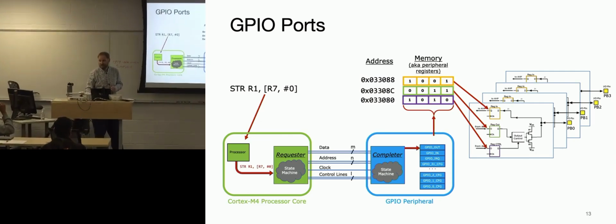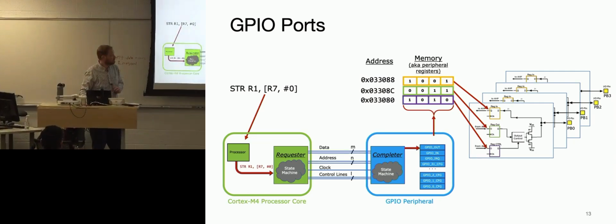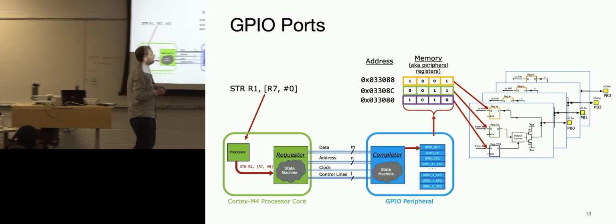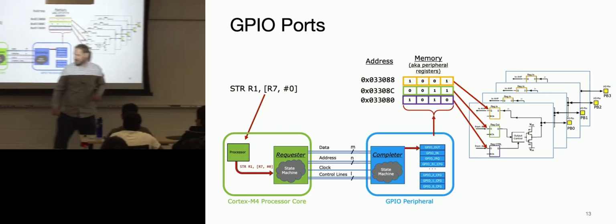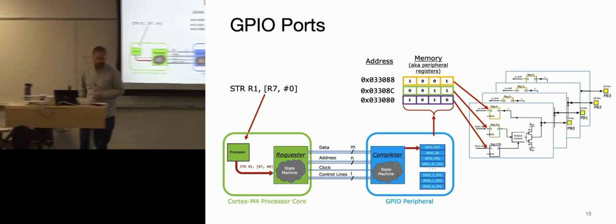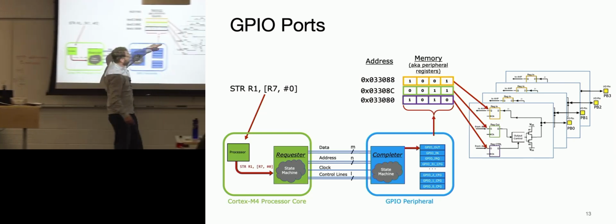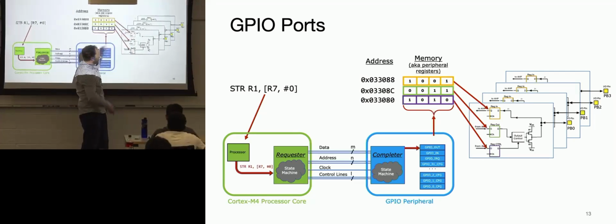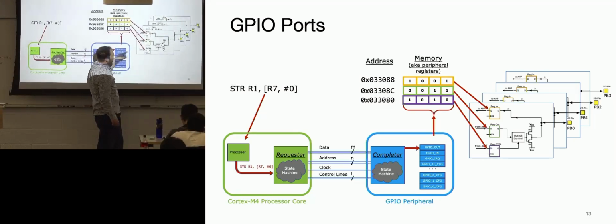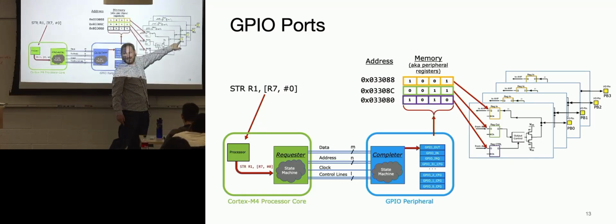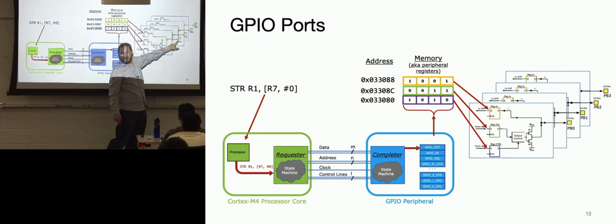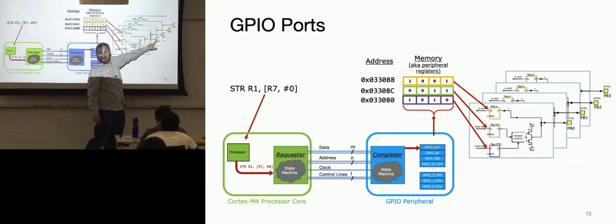Yeah. So the output register is taking information from the pin, like, so you write to the output register by using information from the pin, right? Well, the output register here is the output pushing data out. So you're going to put a store command that's going to put a logical 1 in here or a 0, and that's going to translate to raising this pin high or low. Output to write, and then input to read.